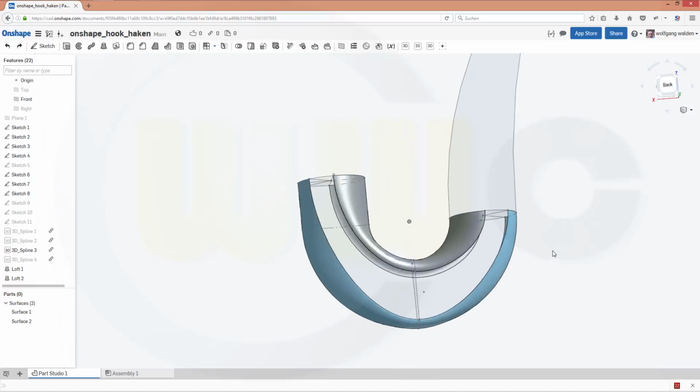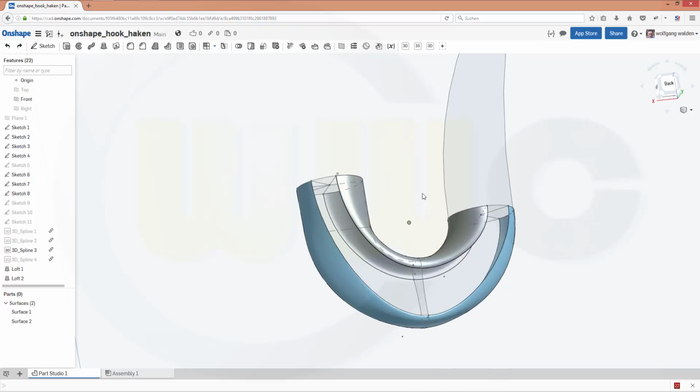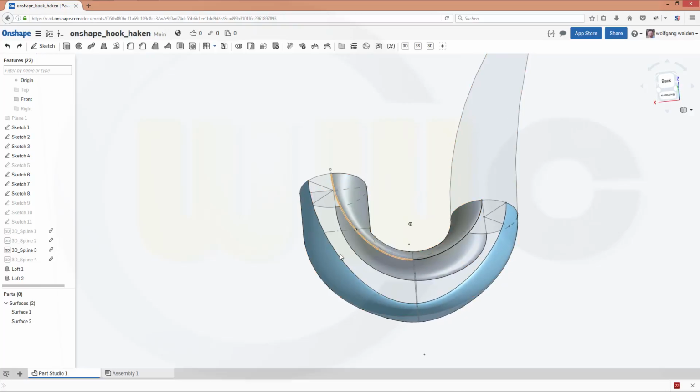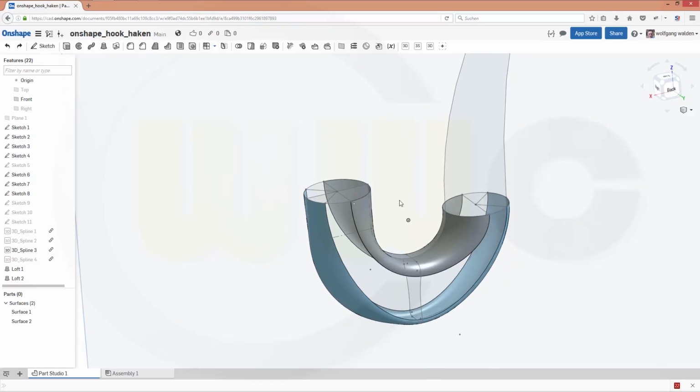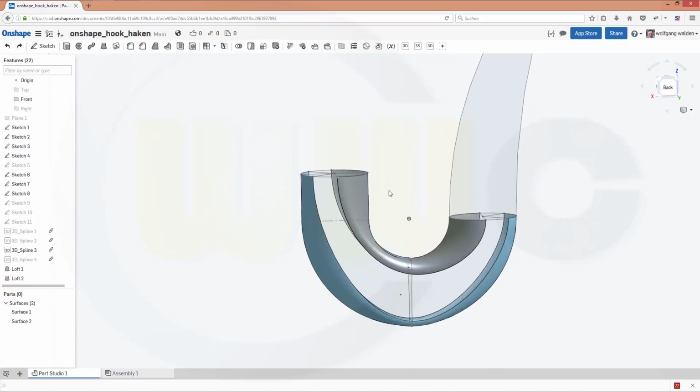So you could try to use this whole surface as a profile, but that's no good. But I could do it in this direction. But you could only go for the end conditions or for the guides. You cannot use guides and end conditions. So yeah, I will go for one solution and you could check the other ones.